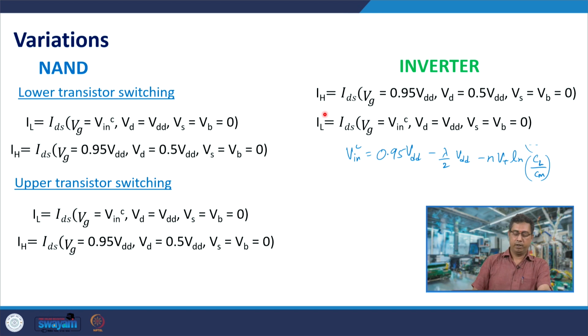In this lecture we discussed the upper transistor switching in a NAND gate and the effective current model for that, and then we discussed how logical effort is related to the effective current models, and how using this approach we can include variations in temperature, threshold voltage, mobility and supply voltage in calculations of logical effort. So, once we can obtain the logical effort using simulations and how it varies with these parameters, one can directly compute thereafter. Thank you.